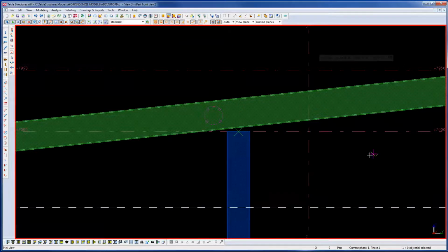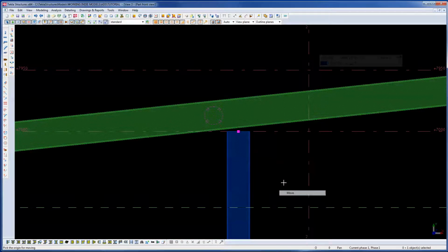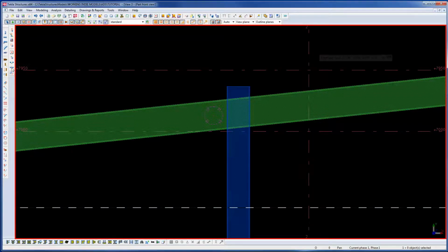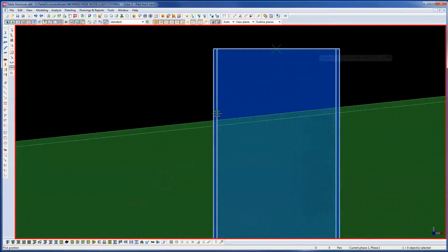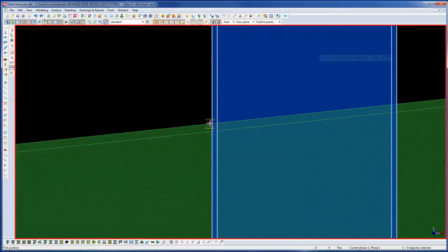Another good practice is just set your UCS to your work plane. So that's set work plane parallel to view plane. So now drag that endpoint up. As you can see, I get this green box at the pick point, and that's telling me that it's pulling it in a perpendicular direction to your X, Y, Z coordinates. I just want to extend past a little bit, and then I'm going to trim this beam back to that point there.